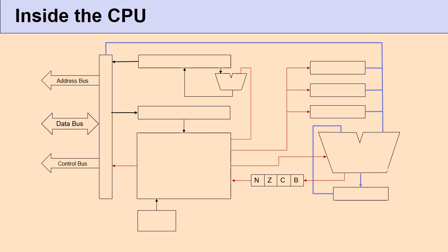Also, the pattern in which these components are connected will have some implications on the instruction set of the CPU. For example, as we discussed earlier, in this particular demonstration here, the ALU output is connected to the accumulator register, which means that any CPU instruction that involves an ALU operation should always have the accumulator register as its output or destination register.